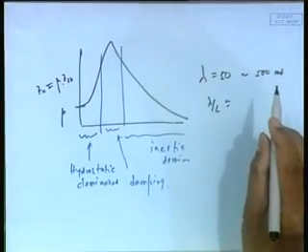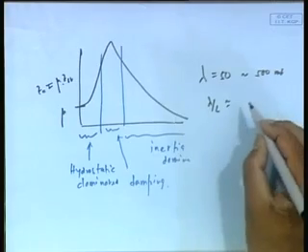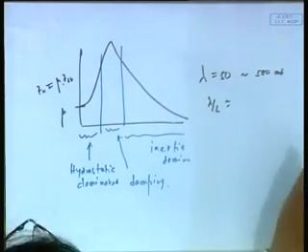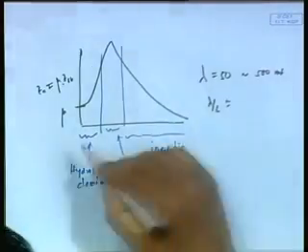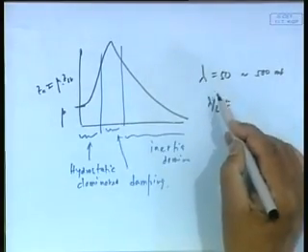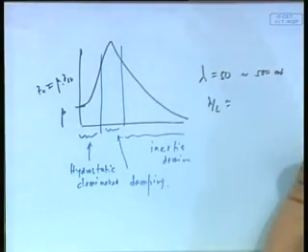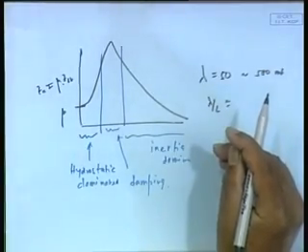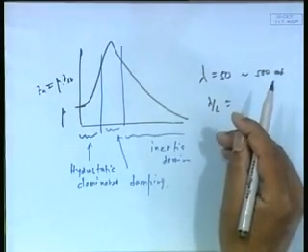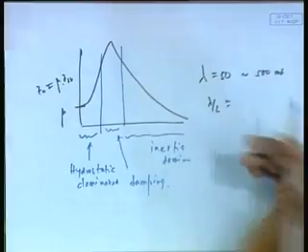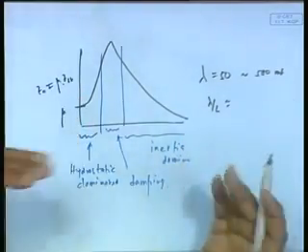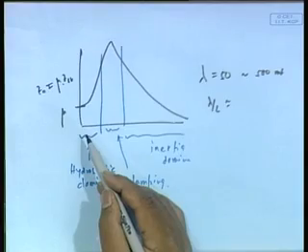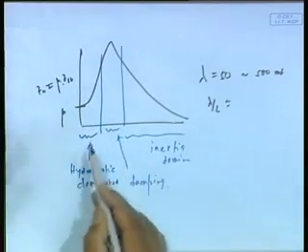Now what happens is, if I take a small boat of 30 meters or 40 meters, let us say a 50 meter boat, then all the waves that exist would appear to be long with respect to the boat, because lambda by L smallest is 1 and goes to 10. So relatively the boat will have a tendency to follow the wave. So if I have a small boat, we are always looking at relatively high frequency motion. Why do I say relatively?